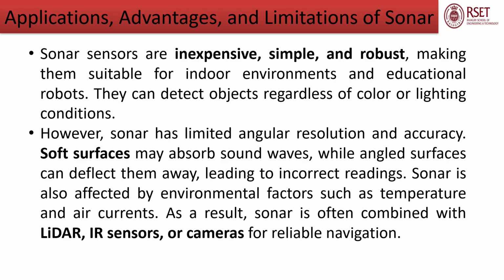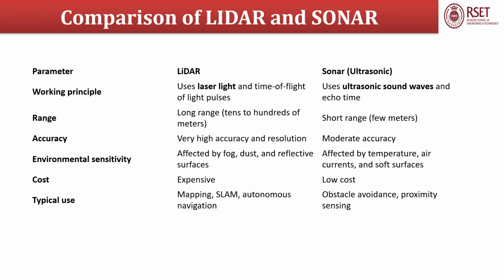However, sonar has limited angular resolution and accuracy. Soft surfaces may absorb sound waves while angled surfaces can deflect them away, leading to incorrect readings. Sonar is also affected by environmental factors such as temperature and air currents. As a result, sonar is often combined with LiDAR, IR sensors, or cameras for reliable navigation.